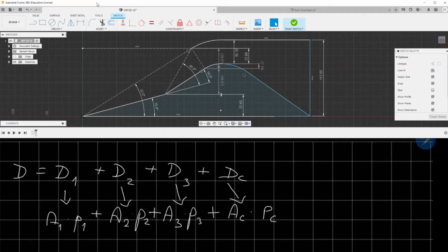You will see if the force you found and force coefficient you found is similar to the force and force coefficients calculated analytically. And force coefficient, CD, you know how to calculate, is the drag divided by Q infinite S. Area, and this area, characteristic area, is this cross-sectional area, maximum cross-sectional area of the diffuser. Something similar you will find in the Anderson book in one of the examples.